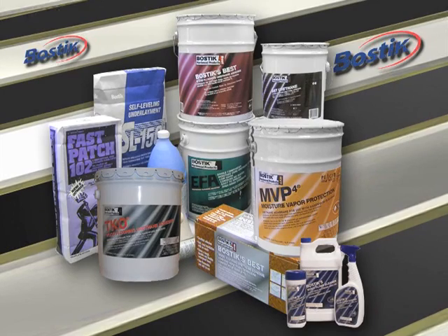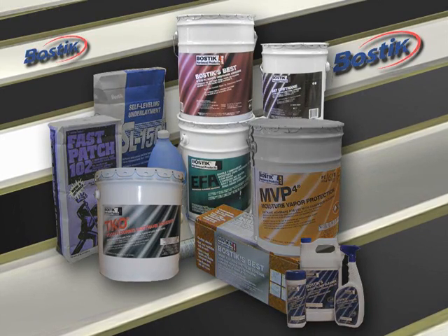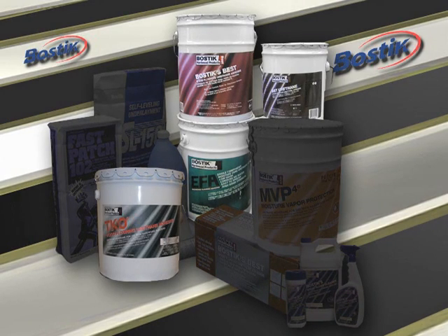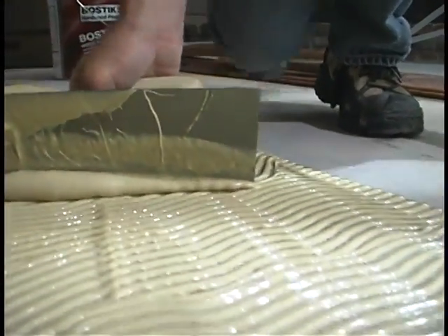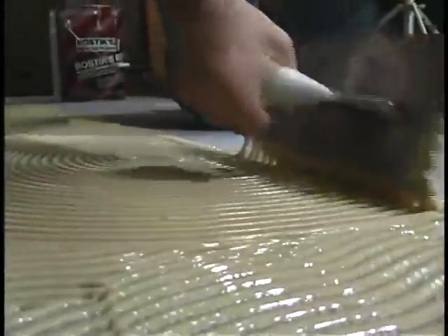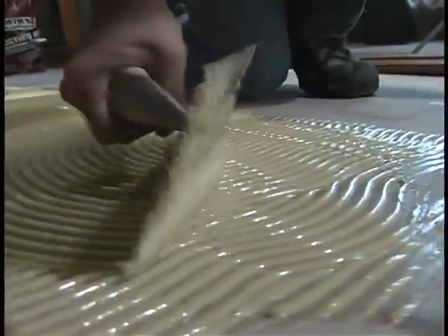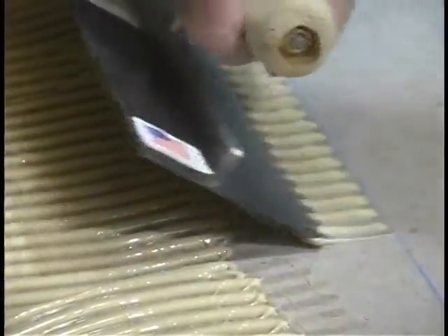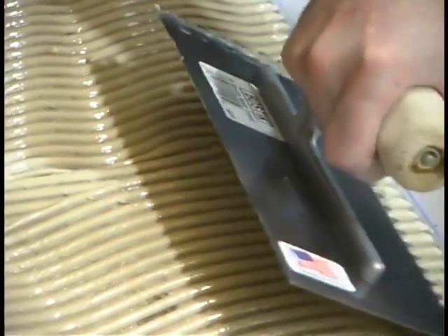The recommended adhesive to use should be chosen from Bostik's family of urethane wood flooring adhesives. Bostik manufactures a variety of moisture-cured urethane adhesives specifically designed for the installation of both solid and engineered wood flooring. Occasionally, you may find that a thin skin has formed over the top of the product when you open the pail. This is a normal occurrence and is due to the inherent nature of moisture-cured urethane adhesives. To remove this skin, simply cut around the inside of the pail with a razor knife, then peel off and discard the cured adhesive. All of the non-cured fluid adhesive can be put to immediate use.